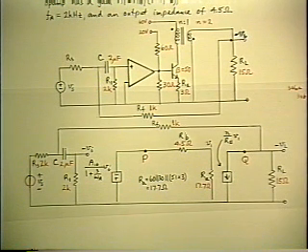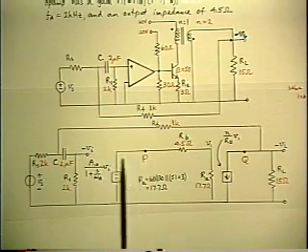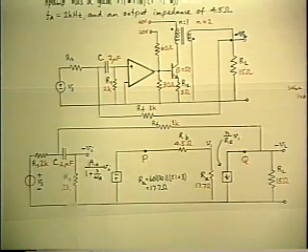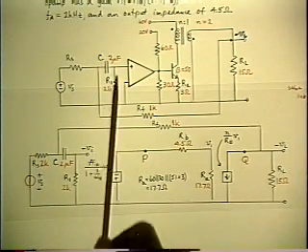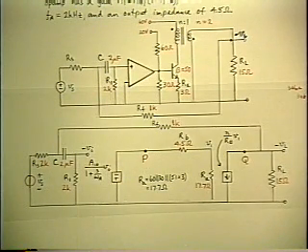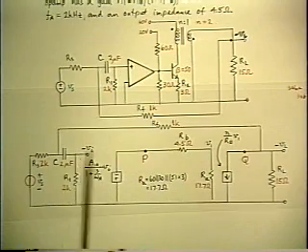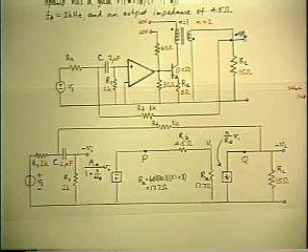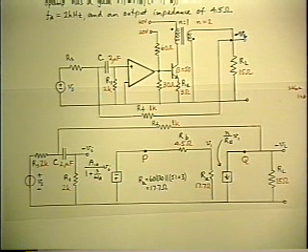Now, in principle, that would be as good a place as P, but in practice it wouldn't be very convenient to do that, or less convenient, because the dynamic range available is less at that point. It's where the signal amplitude is smallest. So you'd have the most difficulty with overloading something and measuring things down in the noise level. So let's not consider that any further.